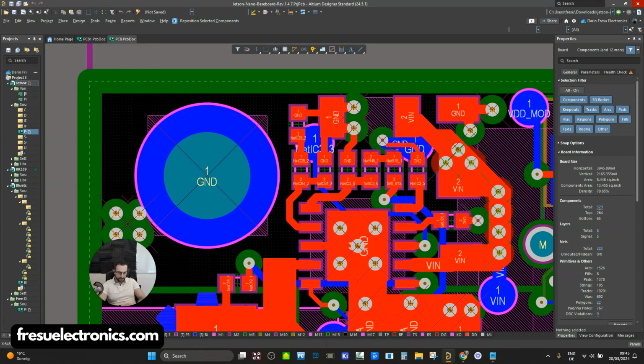Then this transient current has to propagate through the power delivery network, which means it will go through its impedance. So the farther away you have the power delivery network, the more impedance you would have in between. So what we want to do is to reduce this impedance, because by reducing impedance, we reduce the voltage drop, which is created by the current flowing through this impedance.